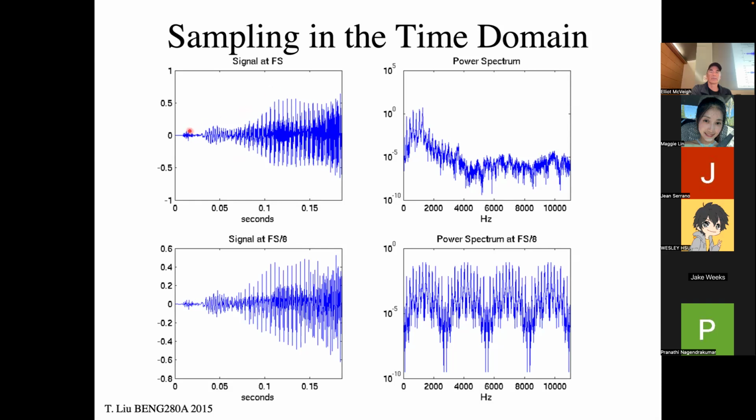We'll sample this at some frequency, basically the sampling frequency. We'll just call it Fs. And this gives us the function that we now have in our computer with those points. And this is time, so this is 150 milliseconds here. If we take the Fourier transform of this thing, it will give us the frequency components that are contained inside this function.